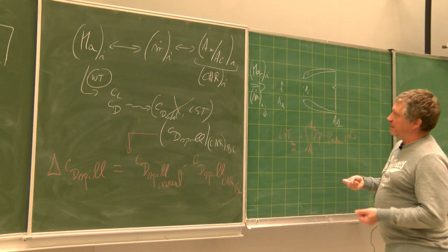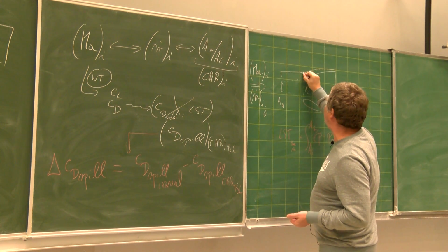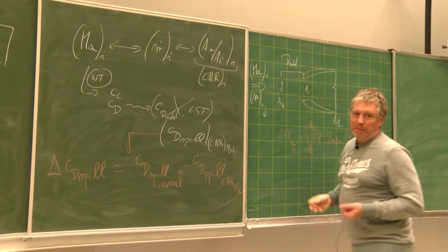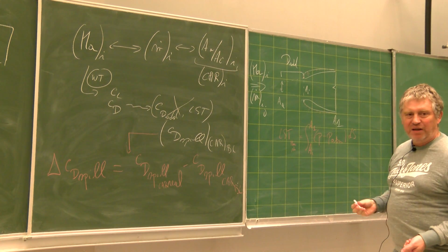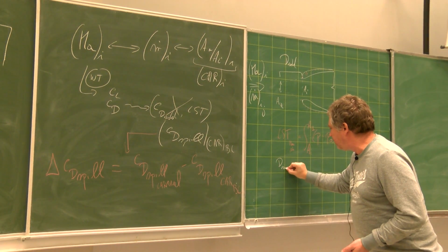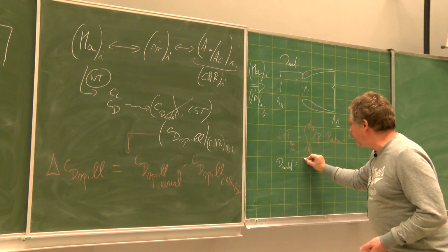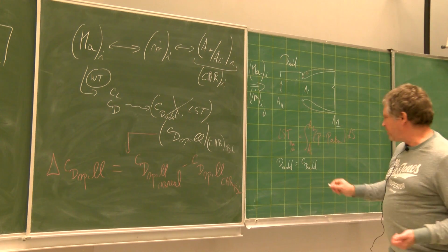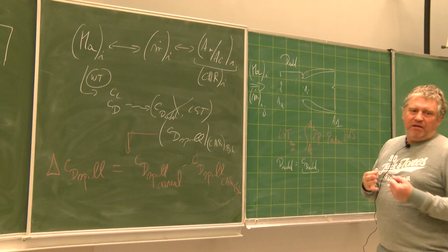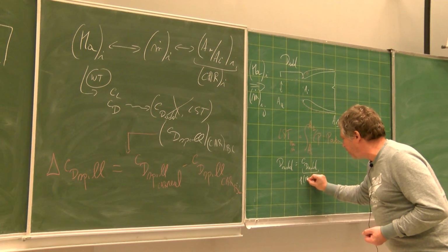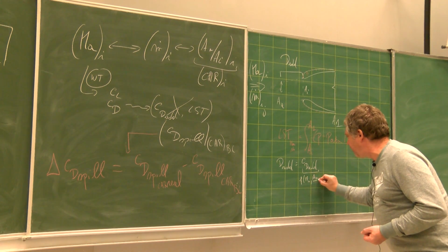Of course, it's not enough, because you also need the influence of the additive drag that is here. But this part is not difficult to have, because we know that the additive drag is only equal to the CD additive that we explained last week. It's just a function of the Mach number and AA divided by AI.